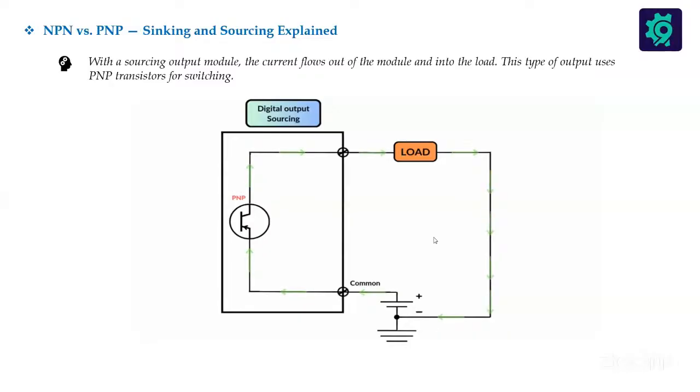Okay. So basically, on your PLC module, there will be labeling for you as to maybe you are supposed to be positive here, or maybe this is supposed to be common. Are you with me? Let's say, for example, I hope you're seeing my screen. This is your PLC, the circuit that you have PNP inside. This is your load, and this side where you have the positive and negative is your power supply.